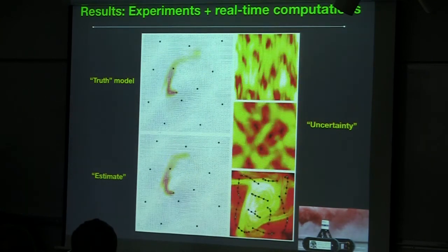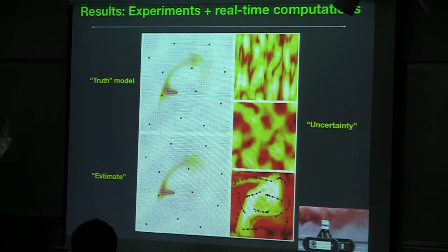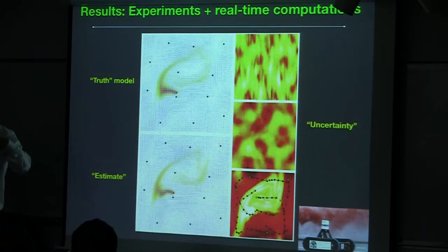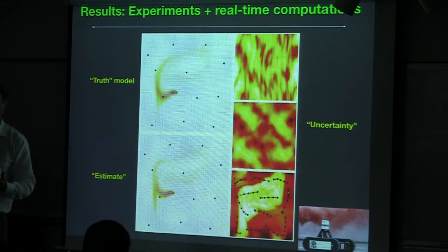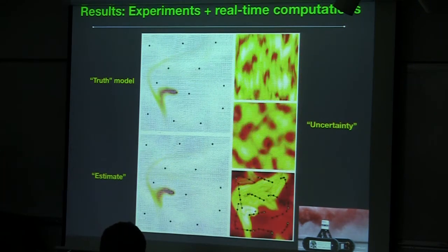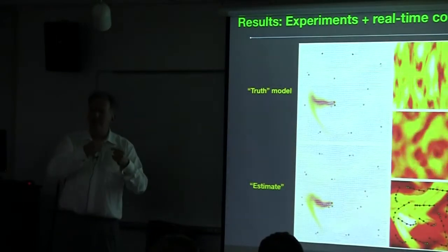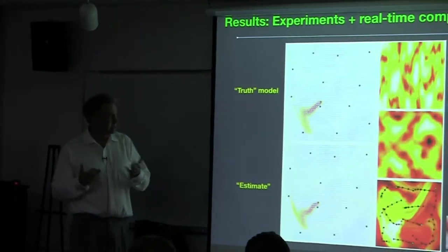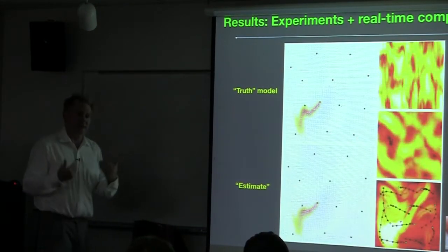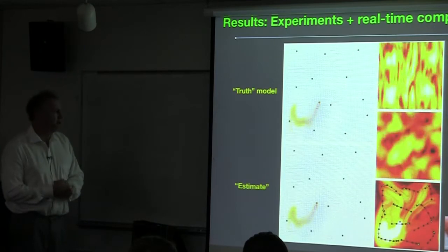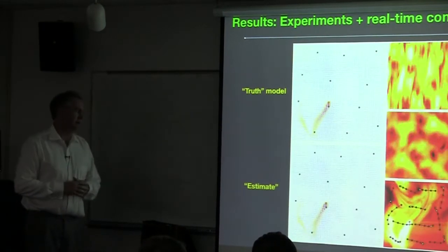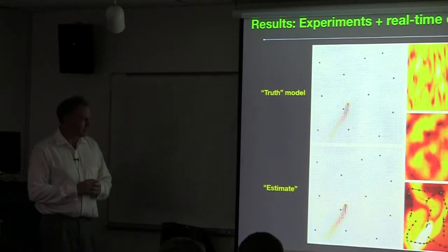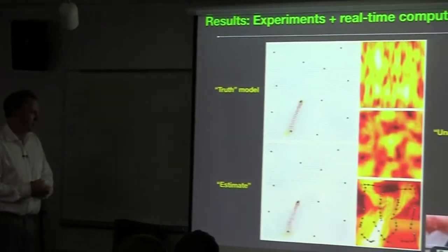And so there are two things going on in this picture. So the first problem that's solved is as the vehicles are moving around, I want to solve essentially a weather forecasting class problem. So I want to look into the recent past and I want to reconcile the measurements of the flow with the actual estimation of the system. So if the estimate is based on what we can observe in the measurements, if the estimate is off a little bit, I need to nudge, so I need to put an update term on the right hand side of my evolution equations. I need to nudge the evolution of the system in order to match the observed data.